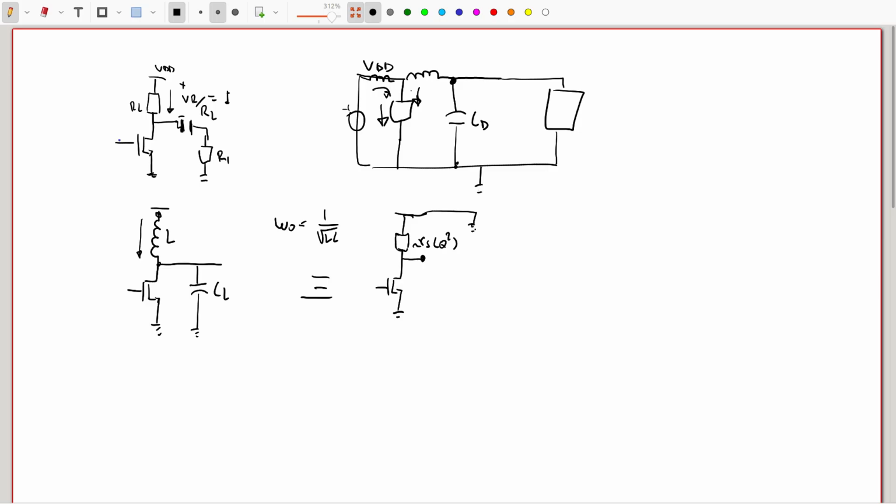Okay, so that is basically the use of inductor. We can also bias the input. We can use a current mirror here. We can probably bias the input with an inductor and then connect this to a source with a coupling capacitor. So inductors are very useful at high frequencies, something that is going to be the topic of the next course in radio frequency integrated circuit design. But we are not really going to use much inductors here.